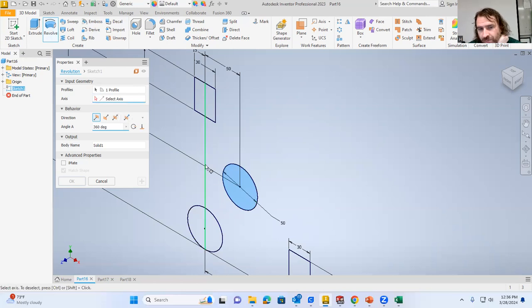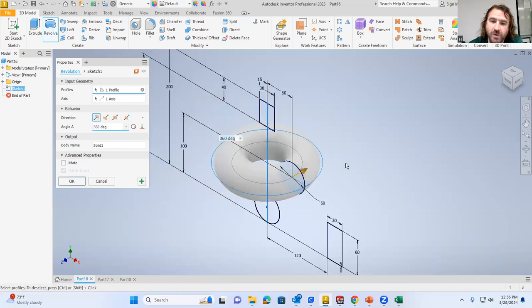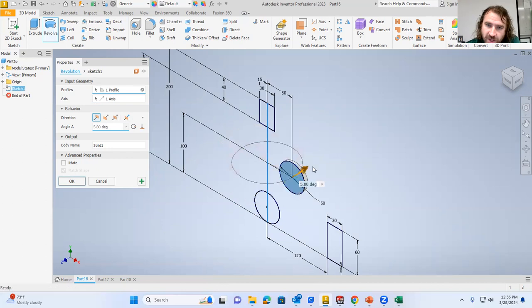It's actually out here. So what's going to happen here is we're going to get a donut, or in mathematics, a torus. So we're going to get this donut shape, and you can see it's revolving. It's adding material in that shape of a circle all the way around, and the axis is going to be directly in the middle.